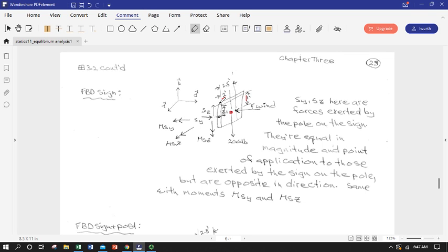So if you want to think about this edge already, the fact that we have a load acting at a radius from where the sign is connected to the post means not only is the post going to have to give us some upward force to react with here, it's also going to have to counteract a moment, which is going to try to rotate this sign in the clockwise direction around an axis that's pointing out here, around the J axis.